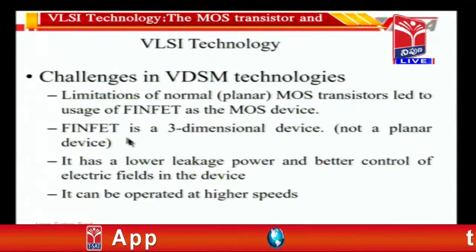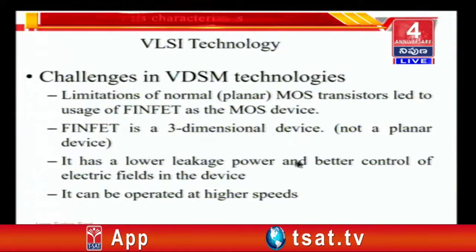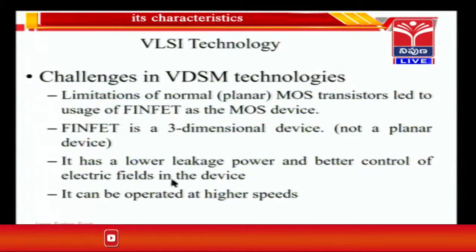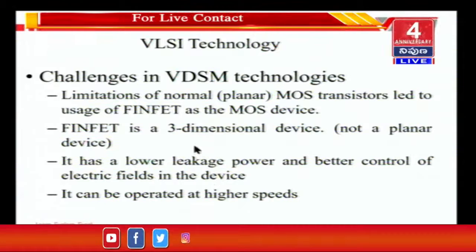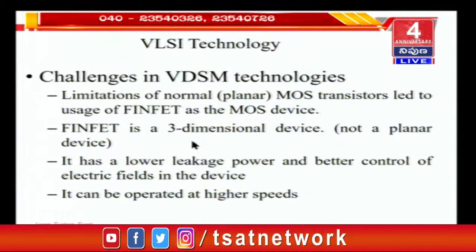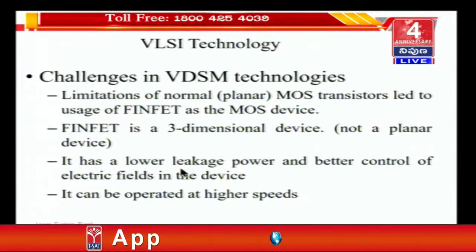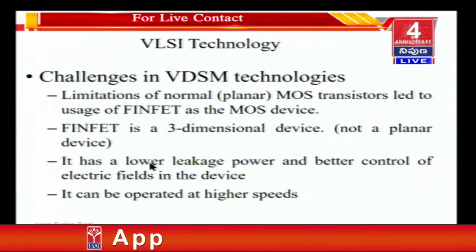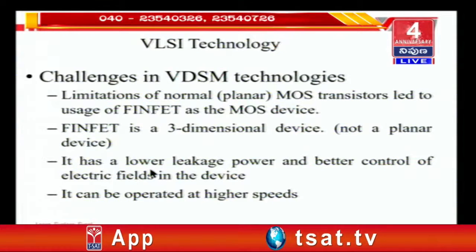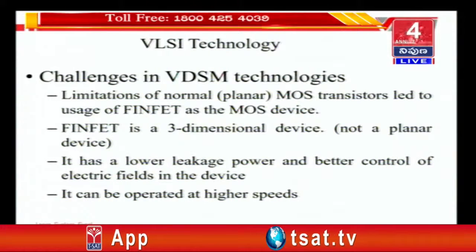The FinFET provides lower leakage power and better control of electric fields inside the device, because the planar transistor, as it shrinks, becomes smaller and smaller. There are what are known as fringe effects in the electric field. You must know what is meant by an electric field. Electric field is basically the voltage per unit distance. So that electric field has got fringes. It is no longer a properly well defined electric field, and therefore the FinFET gives you the advantage of providing better control of the electric field. The electric field is more properly controlled in the FinFET.